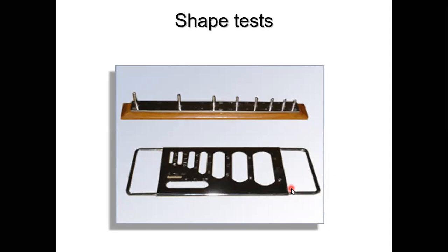Suppose you are taking this slot, 12.5 passing and 10 retaining, correct? Its mean value: add 12.5 plus 10, 22.5, divided by 2, that is the mean value. So that much will be the opening, whatever value comes.